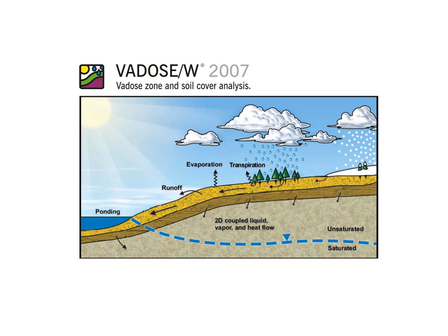Potential evaporation is defined as the amount of water that could be evaporated if there was an unlimited source of water available. However, water does not always evaporate from the ground surface at the potential rate. When a soil becomes unsaturated, the water is not readily available. The actual evaporation is considerably less than the potential value.